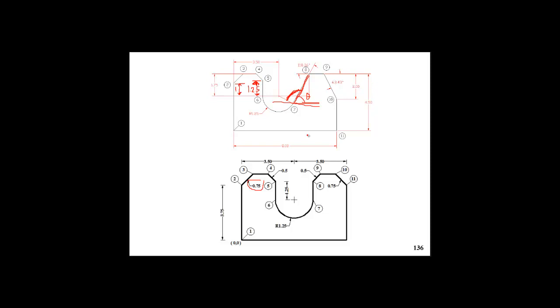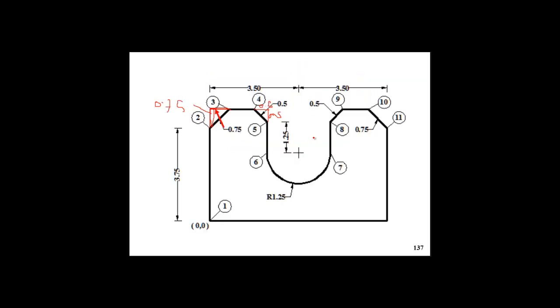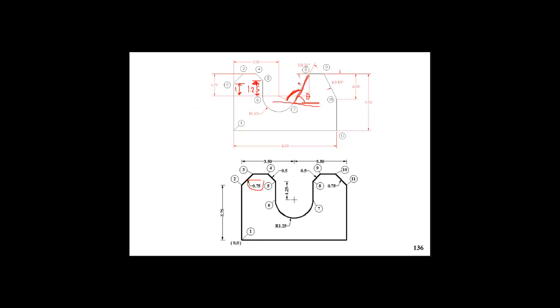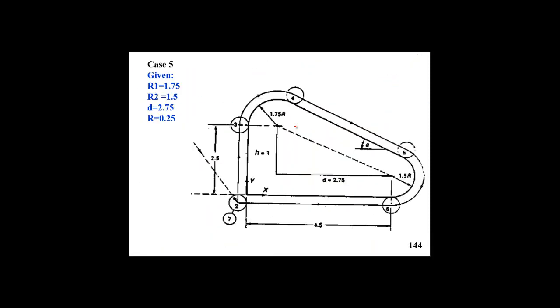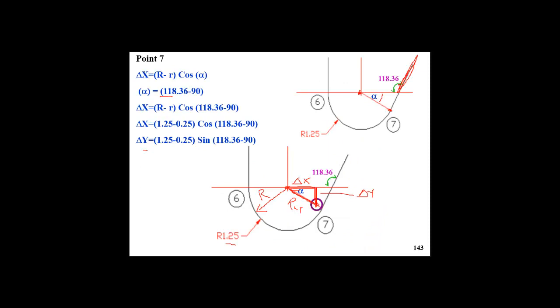Okay. Once we know the slope of that edge, which should be given as part of the workpiece geometry from the dimensions given on the workpiece, we are able to get that angle. Once we know the slope of that edge, we are able to get the complement, which will be the other angle, and that angle and that angle are similar.